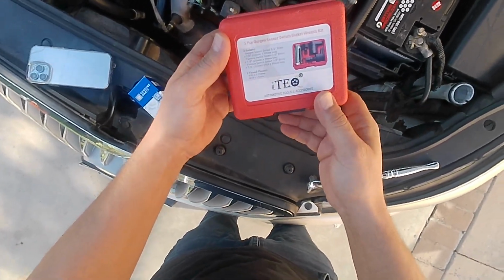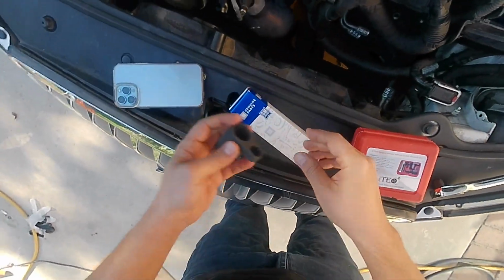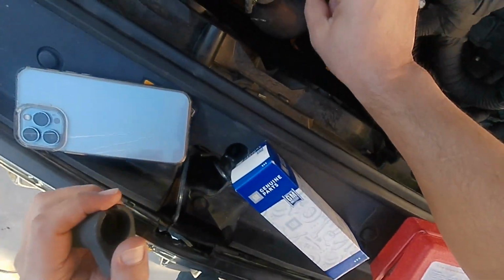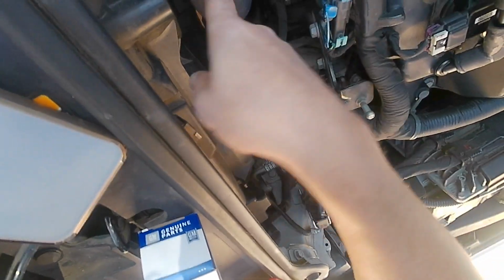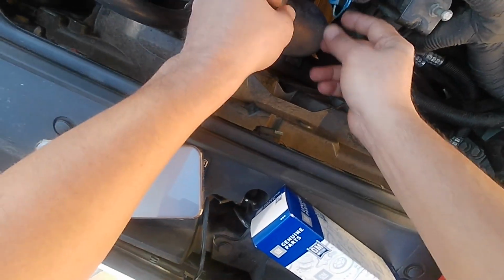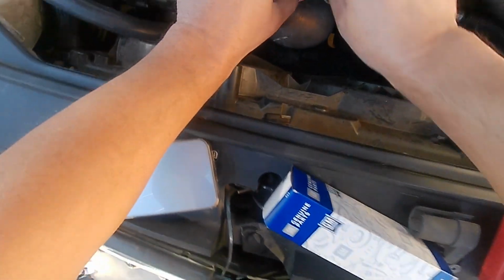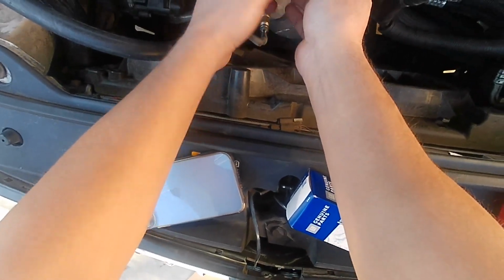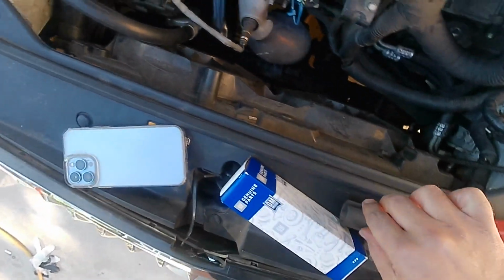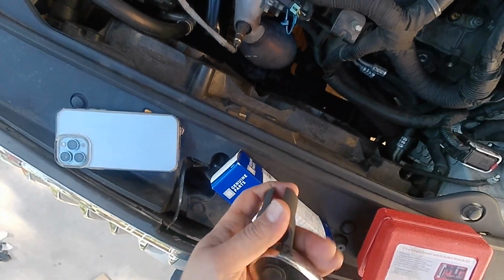This is the tool that I picked up off of Amazon for $20, and it's what I'm going to use to take that oxygen sensor out. So there is one here and one down below, if you can see it down there, and then there is two, one before the catalytic converter, I believe, or by your exhaust. So just remove this lock and lift this up, and then we're gonna pull on the switch. It is recommended that you run the engine for a few minutes, so the heat will let you remove this easily instead of fighting with it.